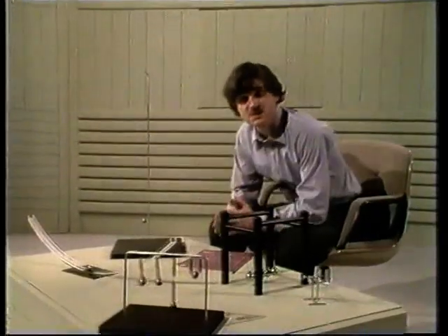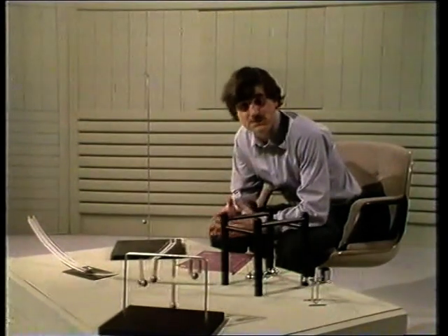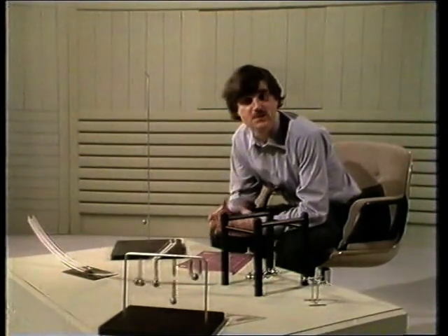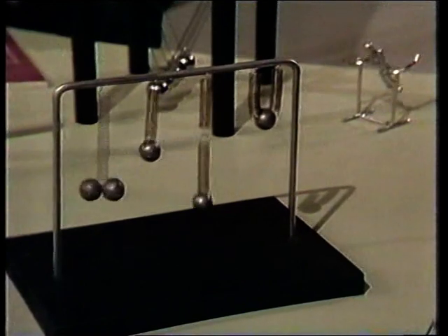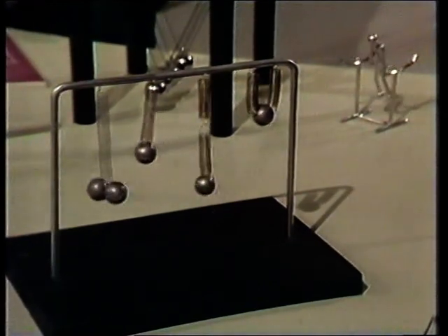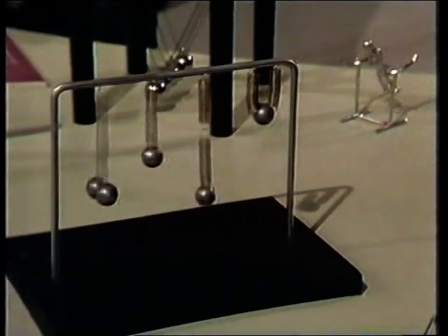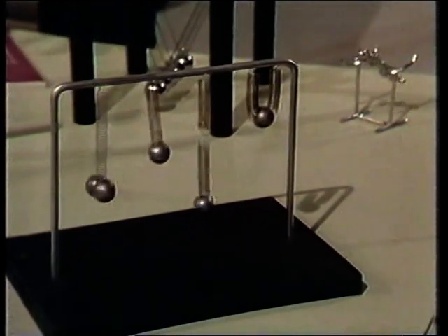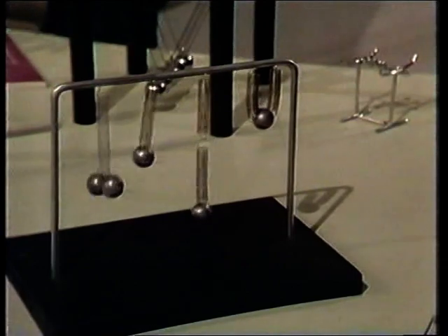In fact, all vibrating systems have this common feature of a spring element and a mass. Well, all of these physical systems look quite different, but they can all be modelled by a simple spring mass system. By changing the spring stiffness and the mass, we can control the natural frequency. And in this way, we can model any vibrating system by a spring mass model.